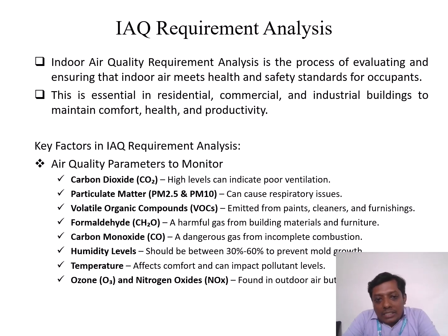What are the key factors in IAQ requirement analysis? Air quality parameters to monitor. The first is very important parameters. What are all the air quality parameters to monitor? First is carbon dioxide, then particulate matter, PM 2.5 and PM 10, volatile organic compounds, then carbon monoxide, humidity levels, temperature, ozone and nitrogen oxides.